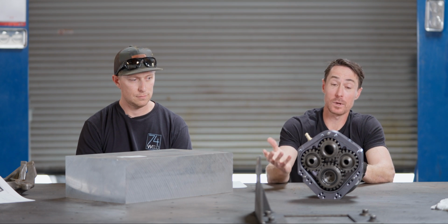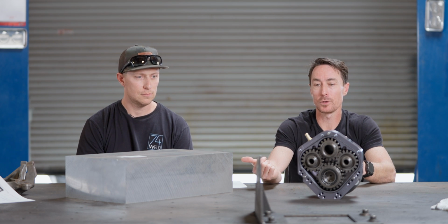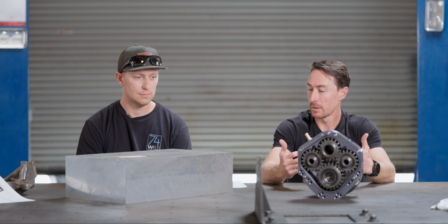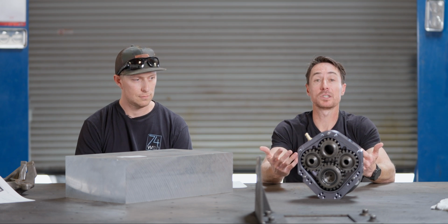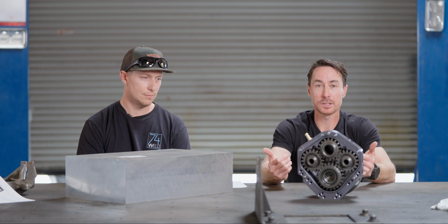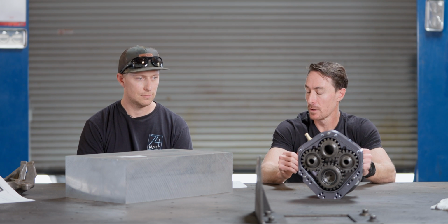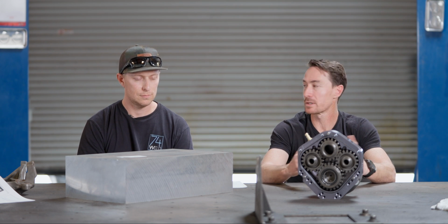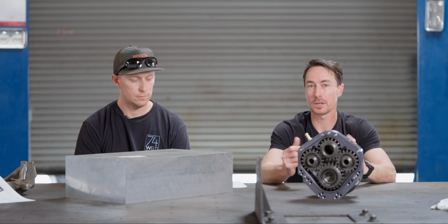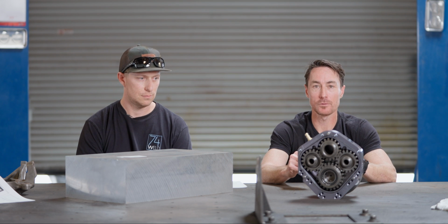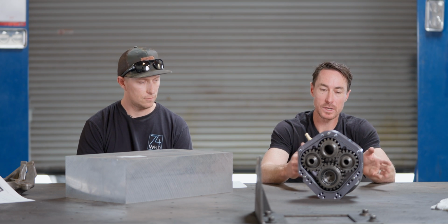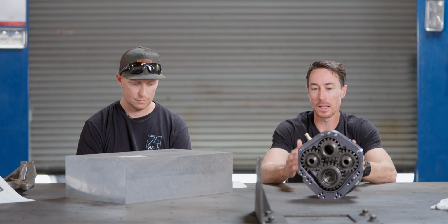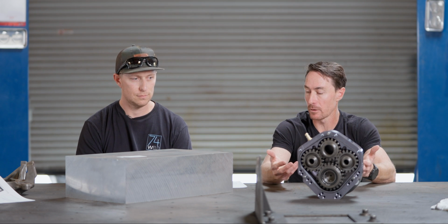Essentially you'll re-harden it up to, let's say, 60 Rockwell, but at 60 Rockwell it's extremely brittle. So you'll be running and you think you've got these great wheel studs, and all of a sudden your wheel studs start snapping off and your tires go flying. That's because the material inherently has a property that allows it to work harden. It's part of the alloy.